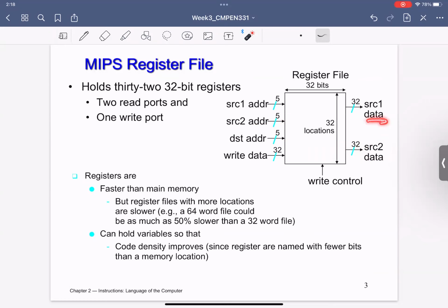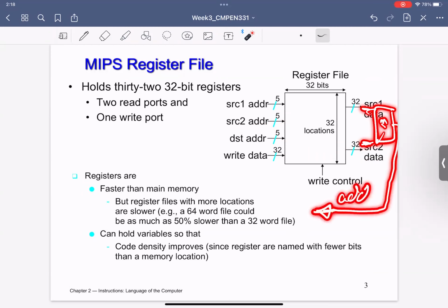Then after that, I will have an ALU here. The ALU will take this and will understand, let's say I would like to do an addition. Okay, so now the addition is ready. Where should I allocate that? This guy is connected here. It's connected with 32 bits because it is an addition. Addition of this plus this, I still have, let's say, 32 bits.